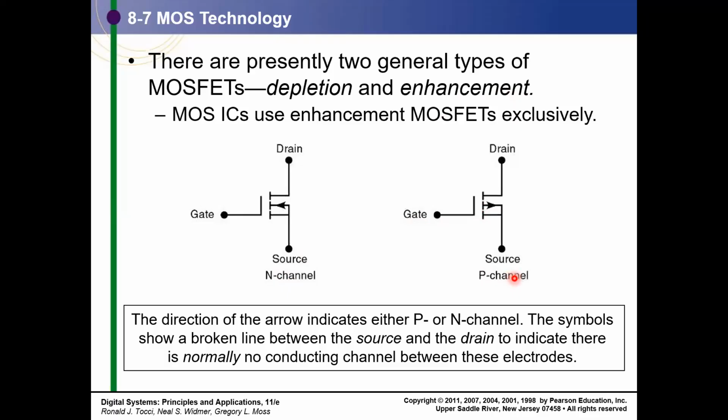Here we have shown the fourth terminal, and it is shown shorted with the source. Here the fourth terminal is again shorted with the source, whereas because this is the higher potential node, in PMOS devices your substrate is connected to the higher potential node. Here it is connected to a lower potential node.